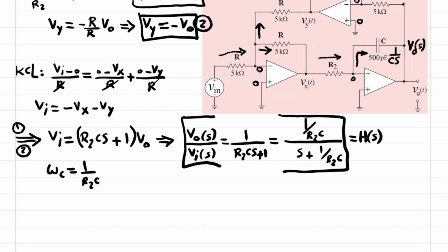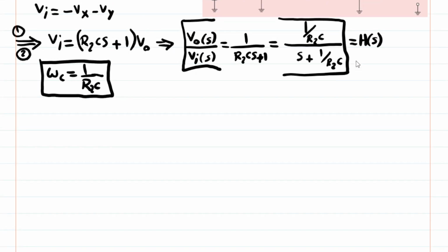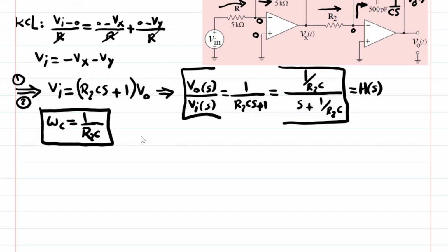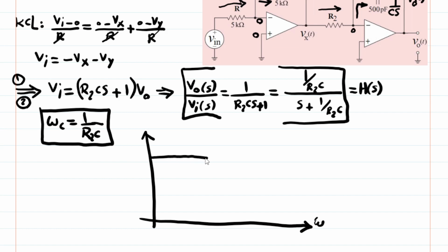Okay, so what is the consequence of this? For example, let's say you want this cutoff frequency. That is the 3 dB cutoff frequency. By that, what I mean is, if I show the hypothetical magnitude response, you would get the response of this low-pass filter something like this, if this is frequency and this is the magnitude response, flat.